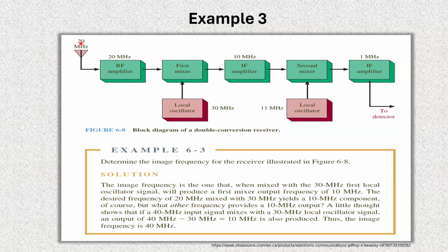So if you bring it from high up there to somewhere lower, and then again to way low, far away from all that stuff, it's going to be even easier to come up with high quality circuitry that does the selectivity, because at this point selectivity is almost a non-issue, and of course the rejection of something else that could bother us as far as imaging or image frequencies.